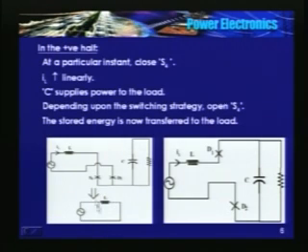In other words, the inductor is short circuited, and this voltage is proportional to the instantaneous value of Vi, which could be negative also in this case. The capacitor is supplying power. The conditions are the same: the output voltage should be higher than the peak of the input.